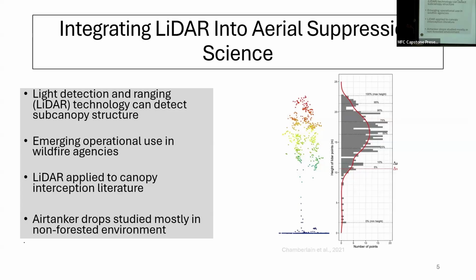So we know that forest structure shapes micrometeorological conditions, yet historically these characteristics have been quantified through field measurements or have been difficult to capture using traditional remote sensing. Light detection and ranging, also known as LiDAR, has increased this capacity. LiDAR is a remote sensing technology that maps forest structure by emitting millions of laser pulses and measuring the time it takes for each pulse to reflect off vegetation or the ground, creating what is called a point cloud.